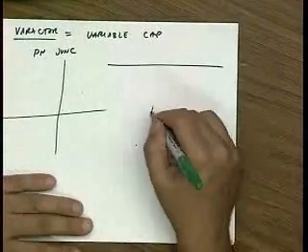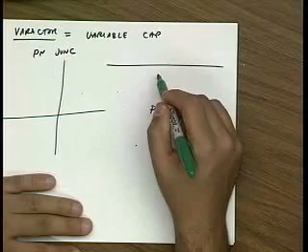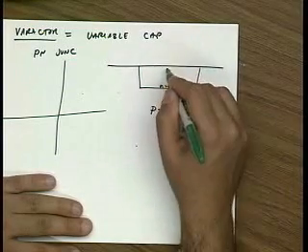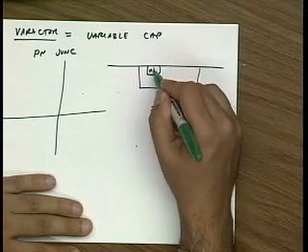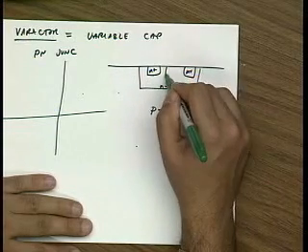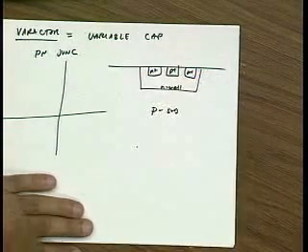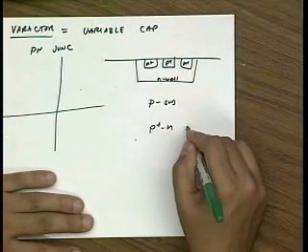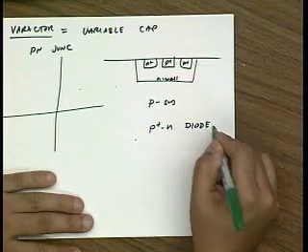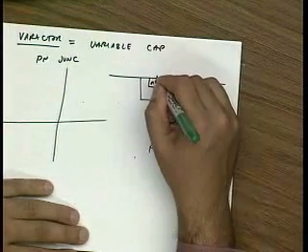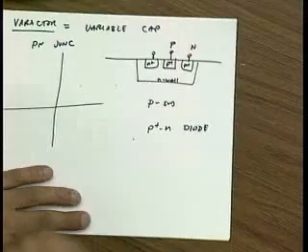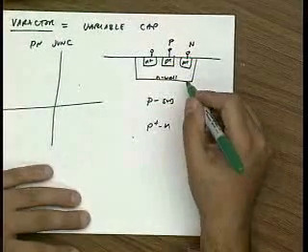In a typical process, let's say you have a P substrate, you would have an N well, and you would introduce N plus junctions and a P plus junction here, so you would have a P plus N diode. This is the P terminal, this is the N terminal.